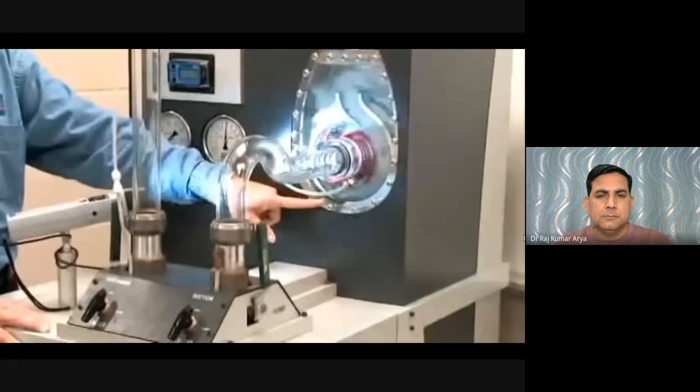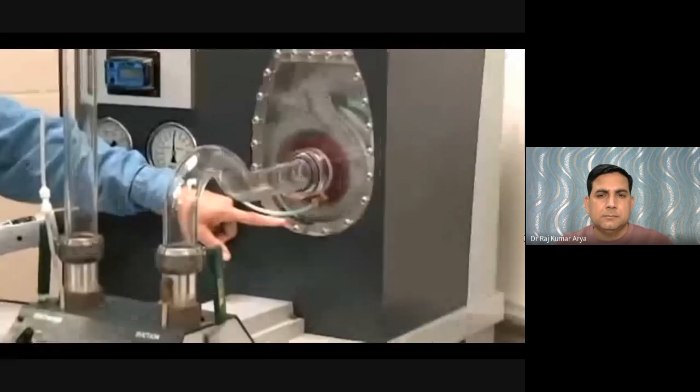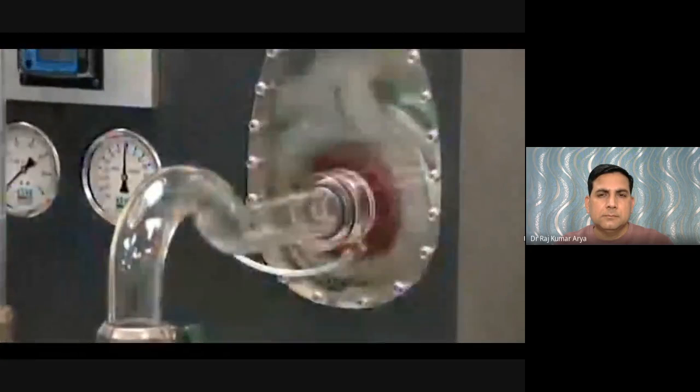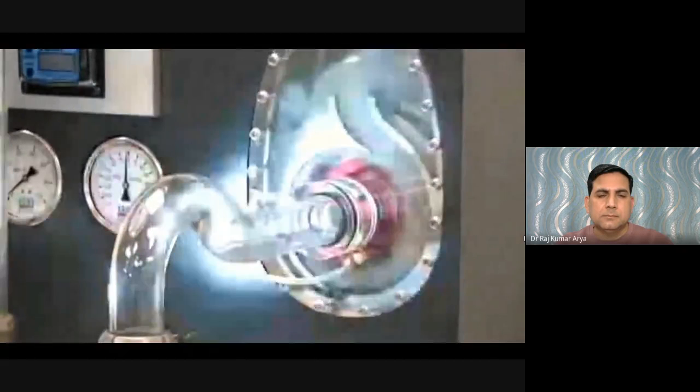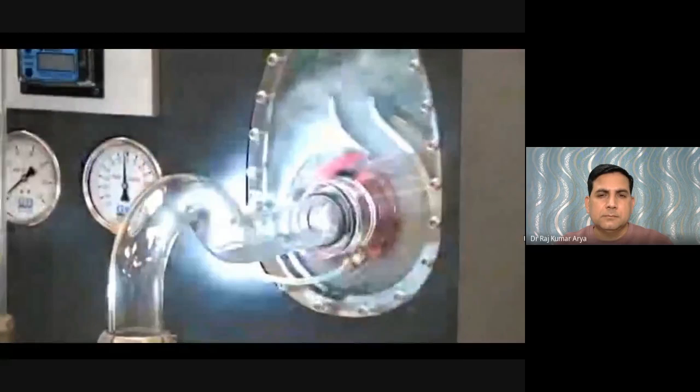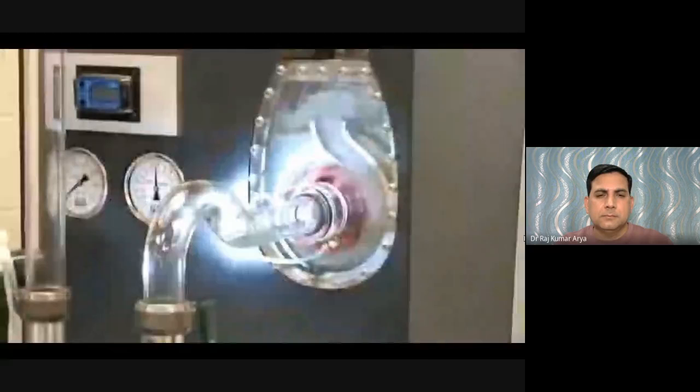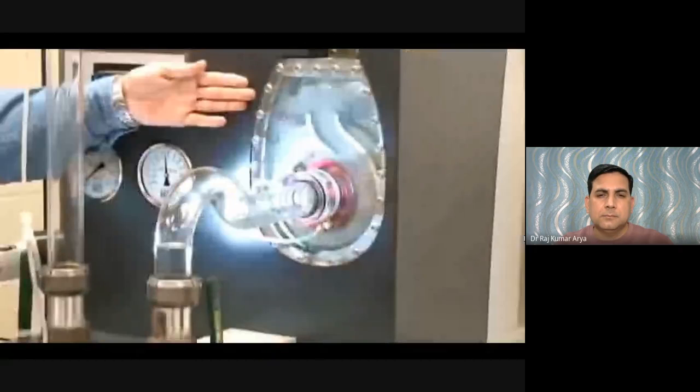As liquid moves up the suction pipe, it pushes all the air ahead of it into the volute casing, where it is handled through the recirculation process. Again, the air is handled off the top, and the heavy water recirculates back down into the volute scroll area. I'll close this valve right now and create a suction line capable of pulling a vacuum. Ahead of it moves the air, pushes it into, handles it through the recirculation process, and once the water arrives, the pump then